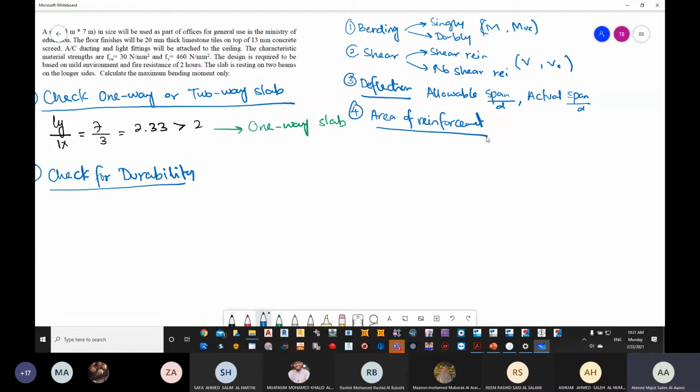Now, if you are talking about over reinforced or a balanced section, in over reinforced, the concrete is going to fail first. Now, if concrete fails first, then the whole section is going to be gone, because the majority of the section is actually concrete. Steel cannot take the loading itself. The same thing for the balanced section. In case of balanced section, both of them are going to fail at the same time. So if any failure has happened, you lost both the materials. So in case of over reinforced and balanced section, the element will directly fail.